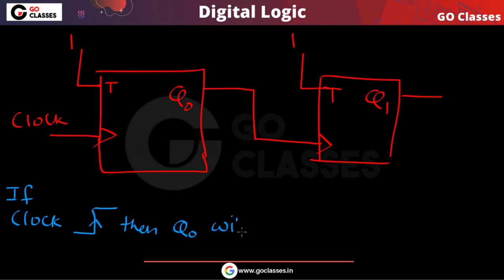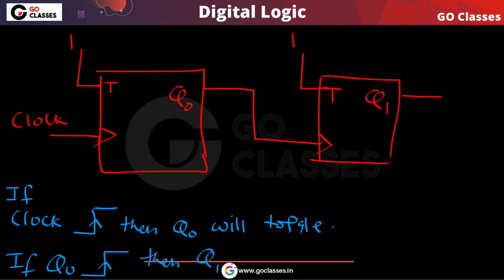Q0 will toggle, because this T flip-flop is operated by this clock. So with every clock pulse, with every rising edge of this clock, Q0 will toggle. Similarly, the output of this flip-flop, Q0, is acting as the clock for the second flip-flop. So with every rising edge of Q0, Q1 will toggle. If Q0 goes from 0 to 1, then Q1 will toggle. So this is the simple idea.